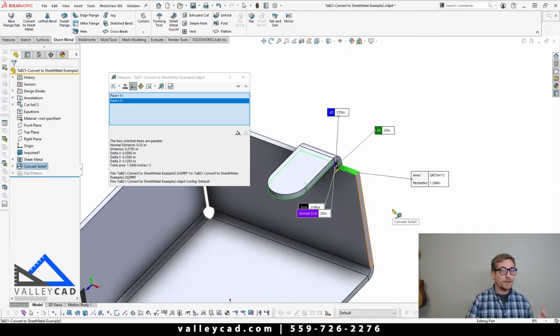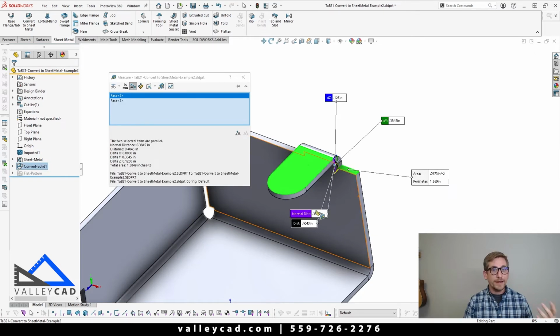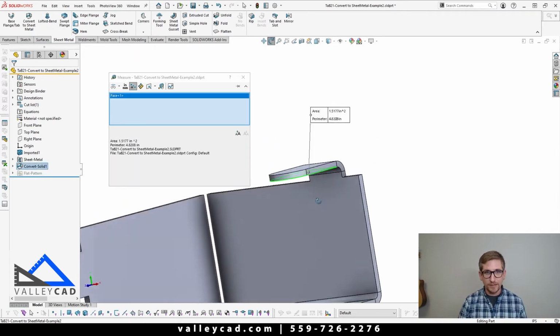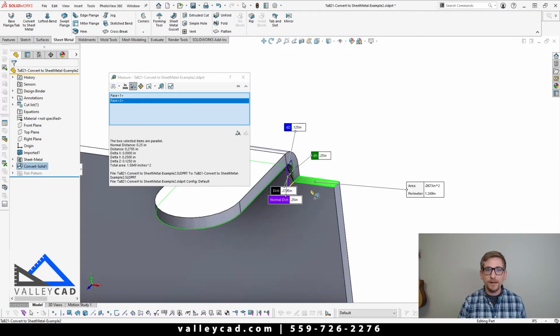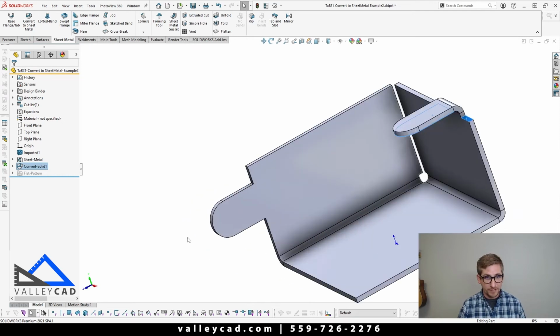Now the reason why I measured it from that inside face is because I was originally working with a 1/4 inch material on it. Technically, this face from there to there is shorter than what was originally there because I extruded inward. So that's why I'm measuring from the inside. So we see from that face to here, it has a distance of 1/4 inch. And once again, I'm using the letter M because that's my shortcut key for measure.